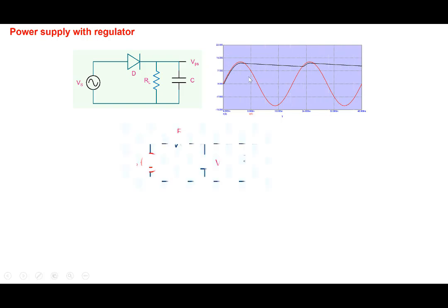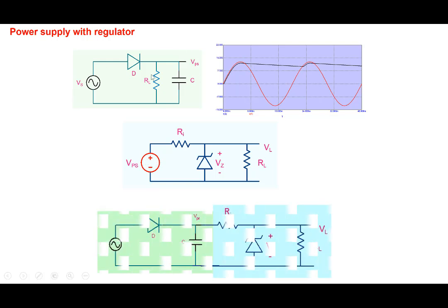So let's use this particular circuit with the rectifier circuit that we had built here with the power supply. So this is the power supply circuit that we had built, and we were trying to increase the value of C to reduce the ripple. But now we'll take advantage of the Zener circuit here, because that can give us a fixed voltage here with very little ripple. Note that here it was just a variable voltage, and now what we'll do is take this out, and instead of this one here, put this particular circuit here.